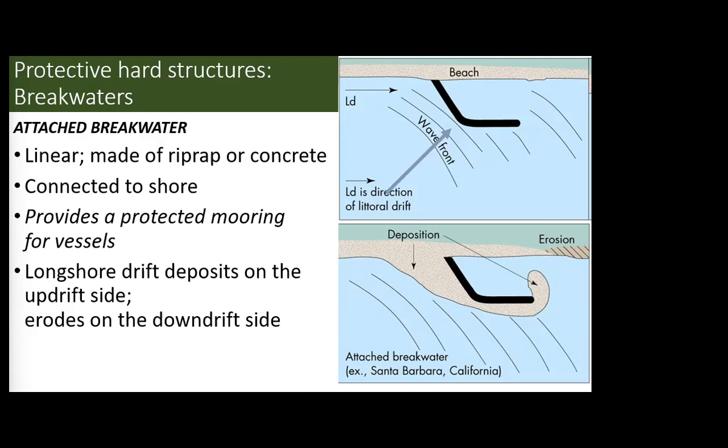So they're connected to the shoreline, and they're going to create another slowdown of longshore drift. So all that deposition gets deposited right in front of the breakwater, so that it'll help you grow your breakwater. So you could maybe plant vegetation on there, make it more stable, make it more of a permanent surface. And as you can see, we're getting almost a spit on the edge of that breakwater. So if we allow that to continue, it may end up closing off that breakwater bay. But instead, if we can take some sediment away from it by dredging, it will keep that breakwater open.